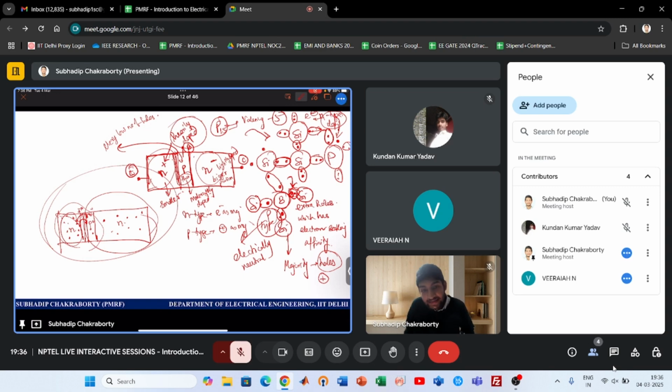Such an internal electric field is developed in that region, the depletion layer, which does not have any free charge carrier, right? So it opposes the flow of such free charge carriers till the time some external electric field is applied to make such flow possible. So what we do, we need to have some flow, so we forward bias this NP junction, or the emitter-base junction is forward biased.